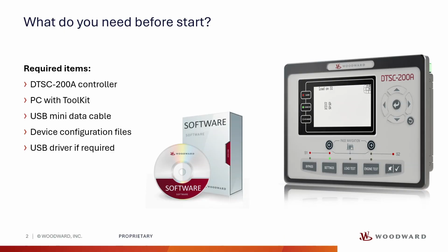To get started with the setup, you will need a DTSC-200A controller, a computer with the ToolKit software installed, a suitable USB mini cable with data transmission, and the device configuration files. Sometimes it may also be necessary to install the appropriate USB drivers.